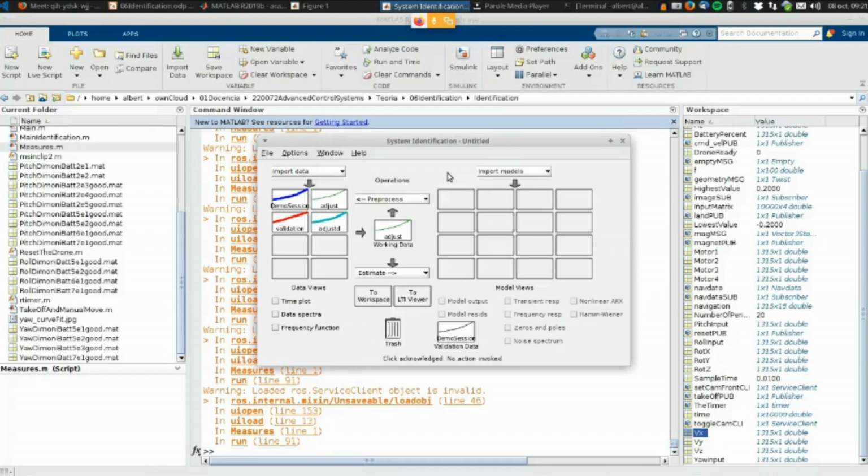So the transfer function is a gain, a dynamic and also a static gain. So it's a relationship between the output and the input as a quotient, as a ratio of polynomials, okay? But nothing about an addition of offsets, okay? The transfer function is a quotient, not an addition. So that's why I remove all the means for the input and the output signals, because I don't want anything about an offset difference between both signals, okay?